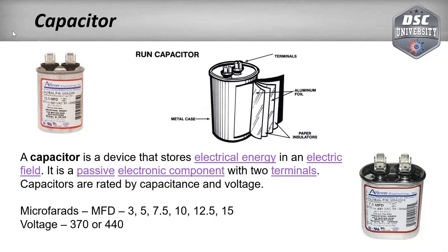A common thing that happens, and I'll use my condenser or heat pump up here as an example, is a lot of times guys will find the outdoor fan motor's not running. And you can take a screwdriver or something and reach in there and spin the fan blade, and the fan motor will start running. And that automatically means that your capacitor's gone bad, because the motor still works, it just doesn't have that kick to get it spinning at the start of the cycle. So we go in there and replace the capacitor, and everything goes back to working like it's supposed to.